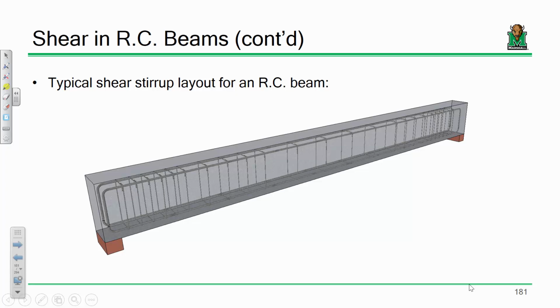But there are also some other reasons. It doesn't really make sense now, but it will later. When you put steel in the compressive region, you get some benefits on your long-term deflection performance. After shear, we'll talk about deflections. And so deflections will probably be a post-spring break topic. But we'll see how rho prime, the reinforcement ratio for your compression steel, shows up a little bit later.